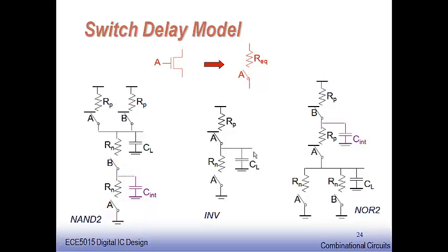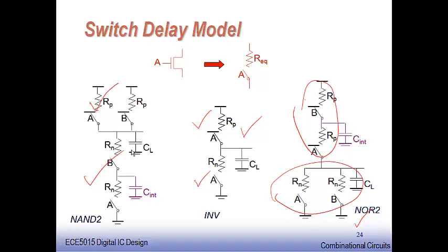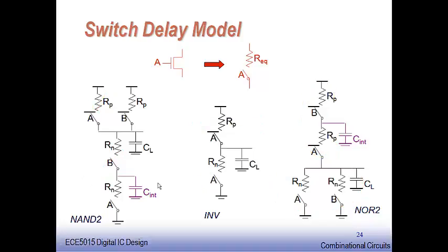Now, how does the inverter compare with this? Let us see. For an inverter you have only one PMOS device at the top and another NMOS device at the bottom. And if I am talking about a NOR gate, naturally 2 PMOS devices in series and 2 NMOS devices in parallel, just the complementary structure of the NAND arrangement. If it is a 3-input NAND gate, naturally, as I told you, you are going to have 3 devices in the pull-down network in series.